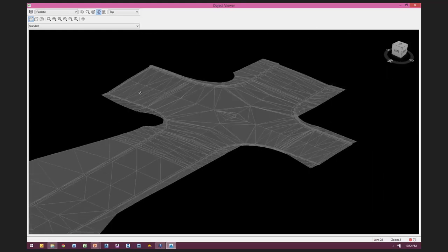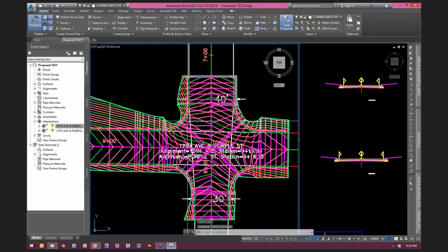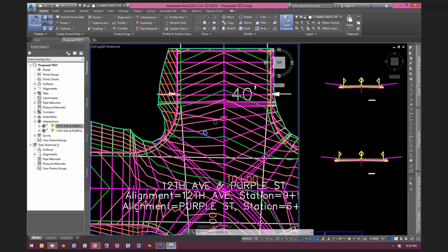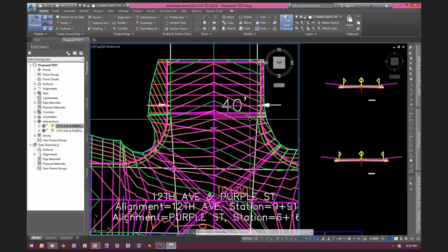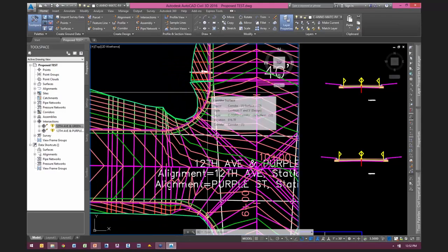There's a jog in the crossing road here. Okay, we would want to define that certainly in our centerline alignment, but we'd also need to define it with our offset alignments. We could have done the same for the primary road. We could have defined those offset alignments. The great thing this does still is that even though we manually defined the offset profiles here and alignments, what it does for the profiles along the curb returns is those are still linked.